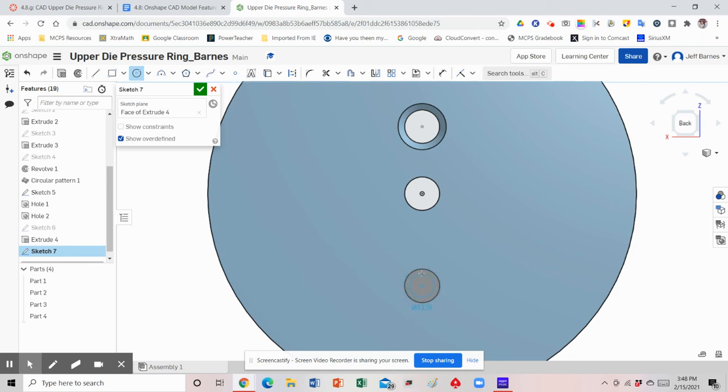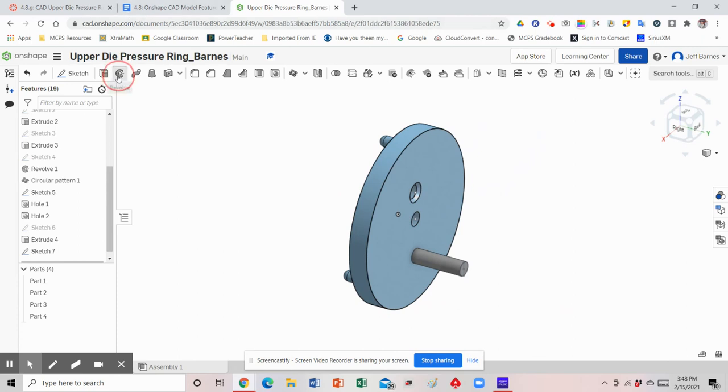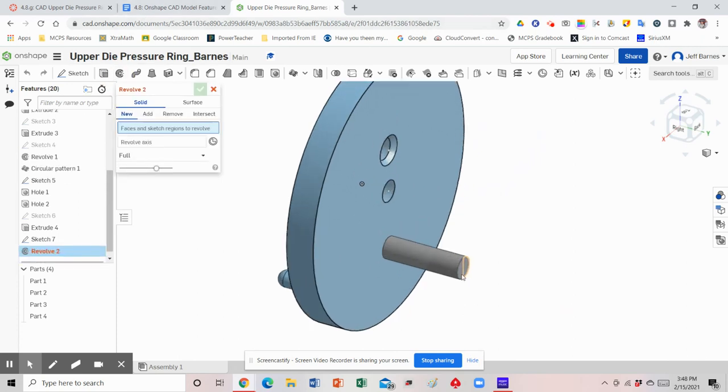So watch, if it doesn't catch for you like it's not doing for me, watch what I do. I'll just make it a little smaller and then dimension it the same. For whatever reason, it just was not catching the edge. 0.25, enter. So now I know they're the exact same. It's always the safest way to be sure you have the right dimension. And then I'm going to cut it in half again, just like I did with the original peg. Okay, I'm going to finish the sketch, and then I am going to revolve it again to give it that rounded cone on top.